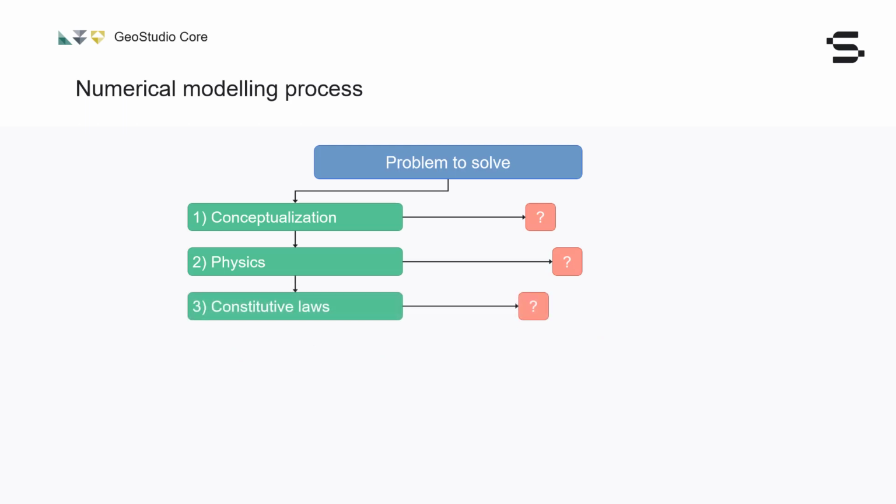As we add physics into our models, we also need to choose which constitutive laws will correctly represent the soil behavior. A constitutive law is a set of mathematical equations that wishes to translate real soil behavior into computer language so that GeoStudio can adequately model the soils in a way that fits the field reality. Constitutive laws exist to represent the stress-strain behavior of soils, for example, or their ability to transfer water and heat, or any other behavior feature we deem important in our simulations.